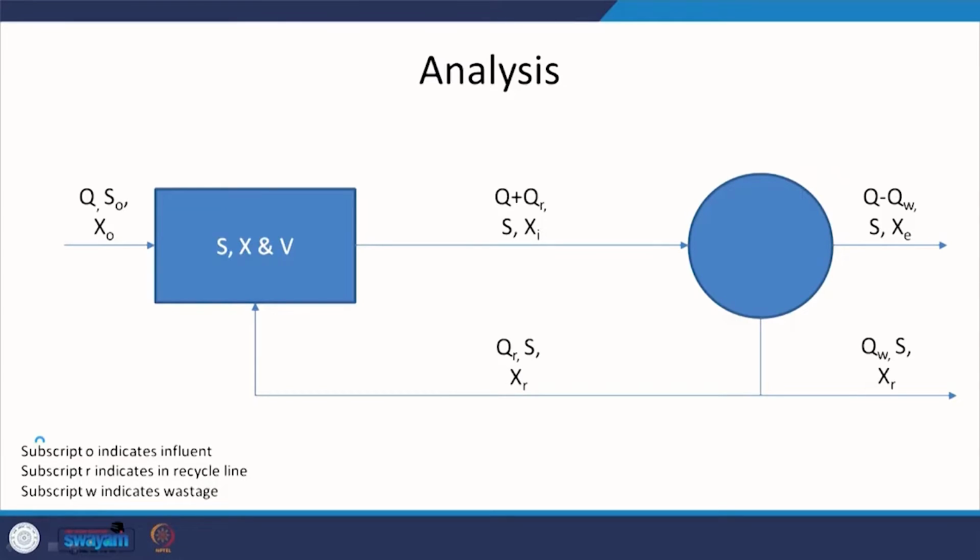Let us move on here. So, analysis. I know that I have my headworks or preliminary treatment, right, and then my primary treatment. Here I removed some BOD, maybe 30%, 35%, or less than 35% BOD removal, and maybe 65 to 70% of suspended solids were removed, right. So, here you are still left with a considerable organic content which is dissolved primarily, and you want to remove that. So, how do we remove that?